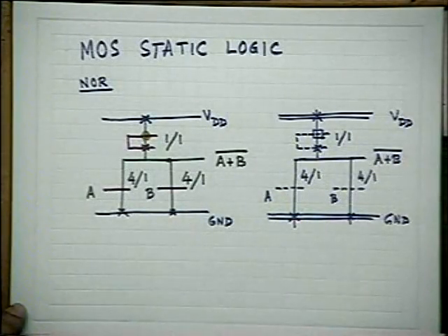So if we are using the NOR logic approach, you know the NOR logic is a universal gate. NAND logic is also a universal gate. So if you are using only NORs, then you are expected to achieve a higher packing density. Let us now go to the NAND.